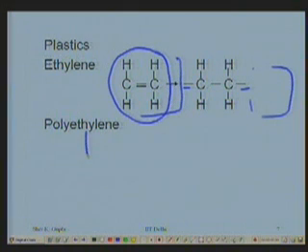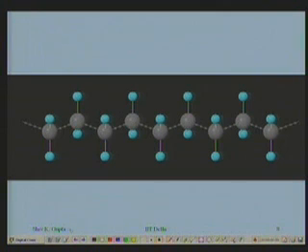Once that happens, I refer to this as polythene or polyethylene. Otherwise, this molecule is an ethylene molecule, which is a monomer, right? This is what I mean by polymerization: that this double bond is saturated, provides the links on both sides, and those links are connected to other monomers in the same fashion. That's what a polymerization process is. Well, this is a polyethylene molecule, chain rather.